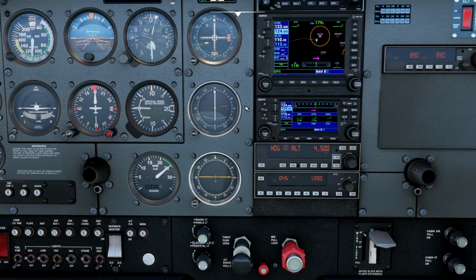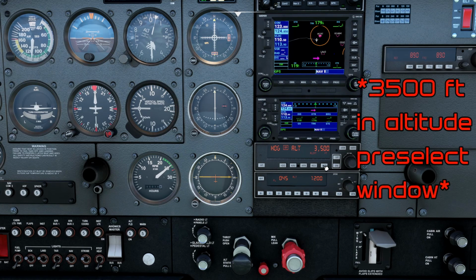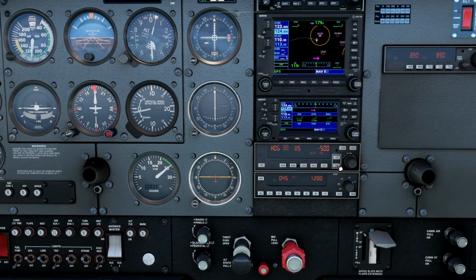Procedures for descent are pretty much exactly the same, except we'll be using a vertical speed down. So I'll go ahead and select 3,500 feet in there. I'll select the vertical speed mode and put a 500 foot per minute descent rate in there. And then don't forget to adjust your power so you don't overspeed on the way down.